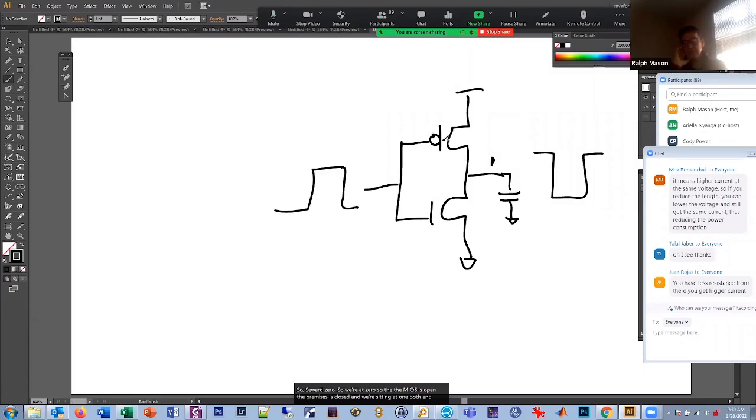These things can provide lots of current, but it's not dissipating any current, because in this situation we have this switch closed, and we have this switch open. And so we know there's no DC current, and this thing is charged up to 1 volt. So it can supply lots of current, but it's not wasting any current, because once we charge the capacitor up, the current stops, right?